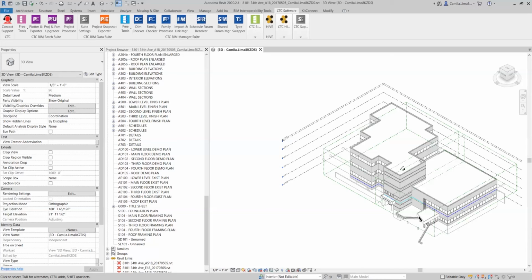The BIM Batch Suite provides us tools that handle daily and weekly automation of plotting and exports, as well as consistently clean up and prep models for submission or archive. Today, I will show you the basics of configuring the Plotter and Explorer, how it runs, and the export results. Also, how to use the Project Processor to clean our project and deliver a cleaned model to other consultants.